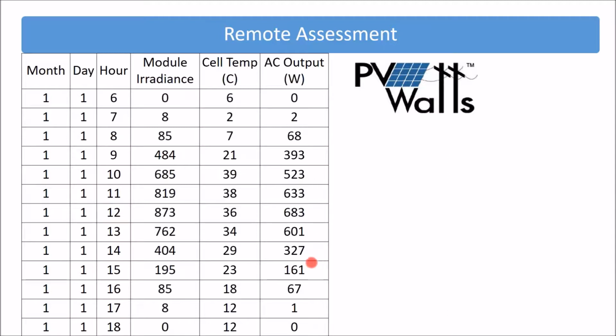To about 2:30, or from about 9 a.m. to about 3 p.m. And anything before or after that, hey, you could pick that production up on a completely unshaded array. But generally in the very early morning and the very late evening, shadows get very, very long.